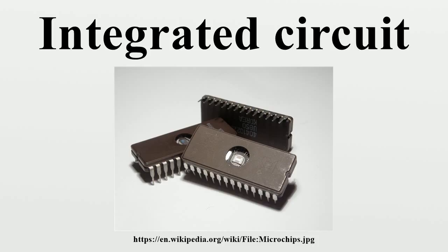Further development, driven by the same economic factors, led to large-scale integration in the mid-1970s, with tens of thousands of transistors per chip. SSI and MSI devices often were manufactured by masks created by hand-cutting rubylith. An engineer would inspect and verify the completeness of each mask. LSI devices contained so many transistors, interconnecting wires, and other features that it is considered impossible for a human to check the masks or even do the original design entirely by hand. The engineer depends on computer programs and other hardware aids to do most of this work.